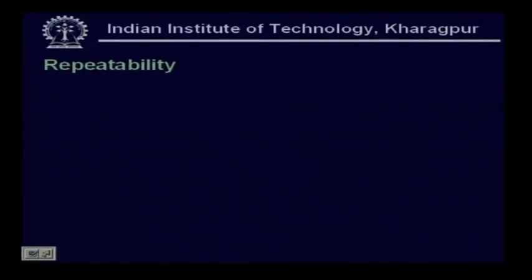Now, repeatability is very important in instrumentation. If there are thousands of instruments in a big plant, thousands of sensors, temperature, pressure, flow, you cannot expect that you will calibrate the instruments every day or once in 7 days. Usually the typical norm is routine maintenance and routine checking of all this calibration, but if there is a fall in the quality of some product, then we will talk about the instrument calibrations or sensor calibrations, otherwise not.